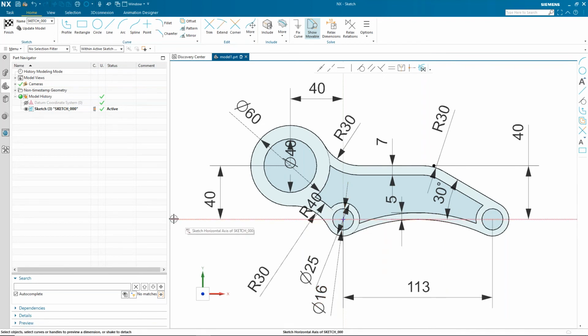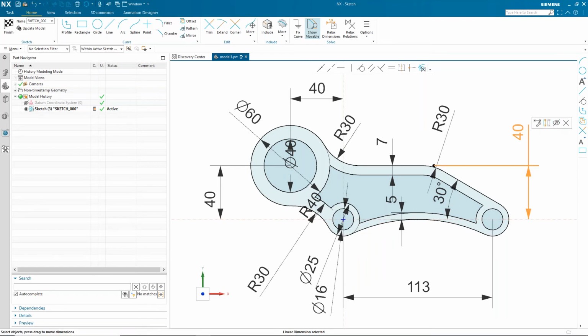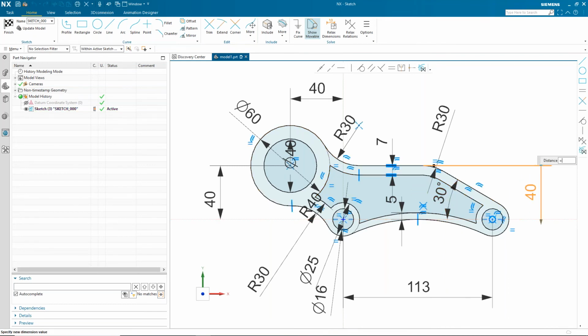So now I have a fully defined sketch, but this one has no expressions on it. So what I want to do now is I want to go ahead and capture some design intent. I could have at any point, what I'll do real quick is I will take this one, and I'm just going to delete this one. You notice now everything's, if I go back here and I'll make this to here, if I pick this value, if I say equals 40, oops, I don't want to do that. You see it creates an expression for it, a P0, because it's the first one, but that's not the one I want to be my expression, so I'm going to put it back to just 40. But you can see my sketch works the way I want it now.